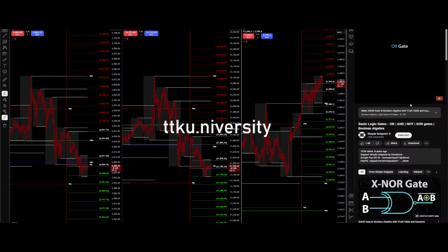So let's see what exactly an OR gate is. An OR gate performs a logical OR operation. We've seen the logical OR operation in our previous tutorials where we discussed the basic Boolean operations. So these operations are practically carried out by these logical circuits. The output is high, that is the output is 1, if any of the inputs is 1. The output is low if all the inputs are low.